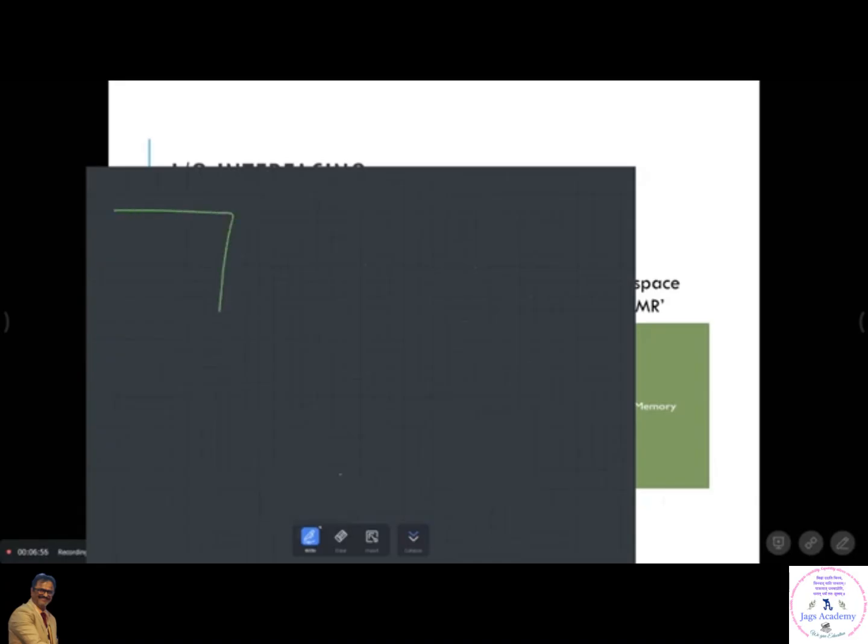This is your microprocessor. Okay, this is your 8086 microprocessor. And you all know that this has a D15 to D0 data bus, and an address bus starting from A19 to A0, and it has M/IO bar. It has a read signal and it has a write signal.